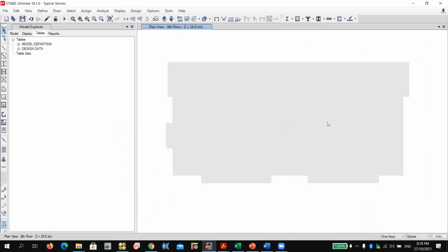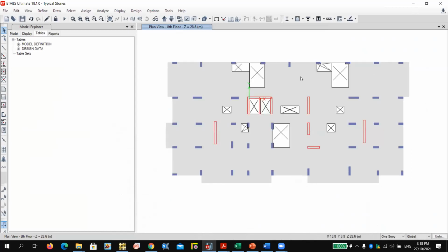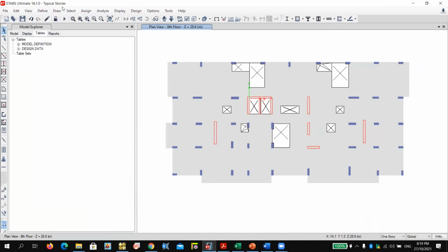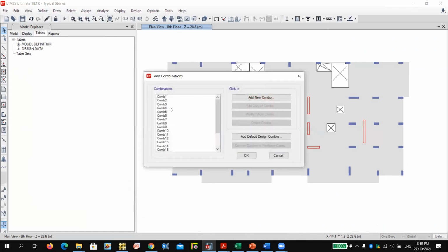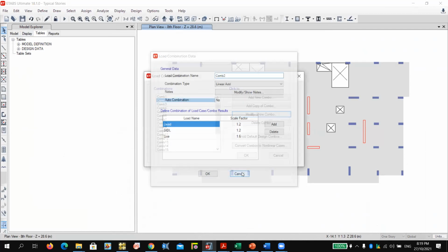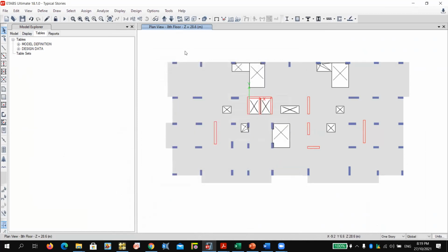So now we know the displacement, we know the sway. We can know the reinforcement of each column. Is the column pass or not? How to do this? Go to define the combination for the ultimate case, which is for the gravity load system only: 1.4 dead load, 1.6 live load, and you can check the capacity of the building or capacity of the columns.